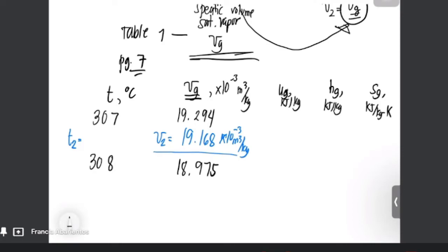Okay. So, doon na tayo doon sa internal energy at saturated vapor. We have 2551.8. Sa baba niya is 2550.1. Dapat may ruler kayo ha. Kakaduling to na steam table. Sa HG naman, we have 2734.